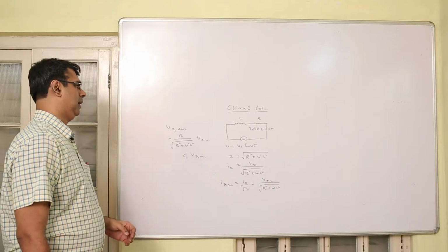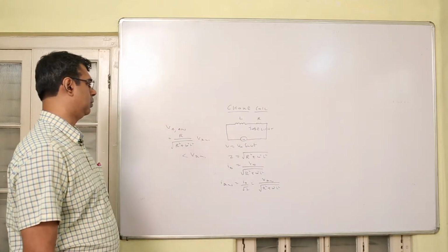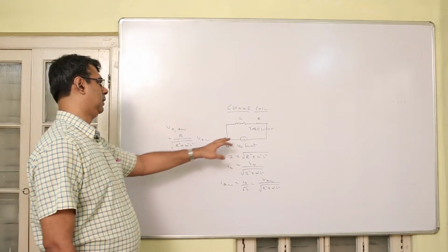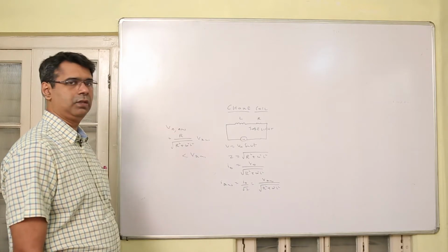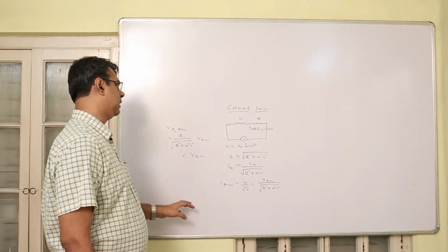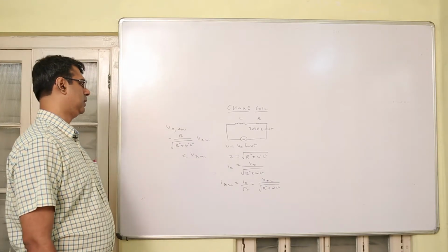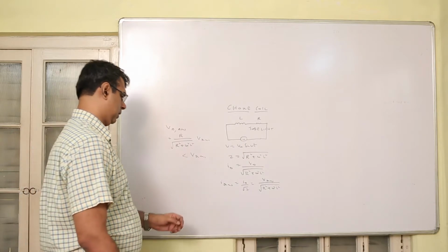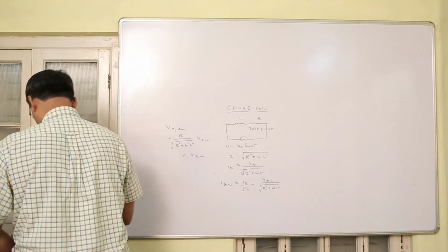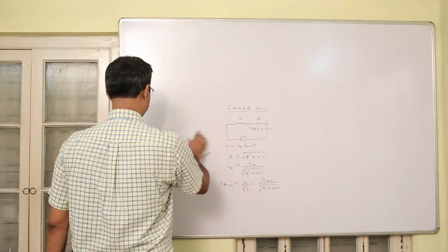So by attaching an inductor in series with the tube light, we are able to ensure that the voltage delivered across the tube light is less than the RMS voltage of 220 volts. Secondly, an inductor gives zero power consumption, so it is a better alternative to applying a resistor in series. So this is one practical application of zero power consumption of an inductor.